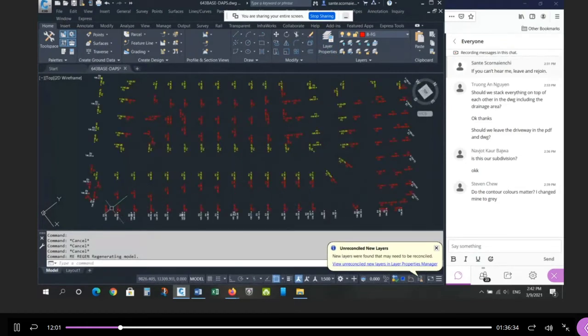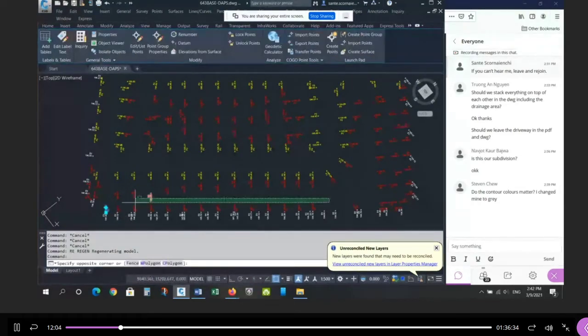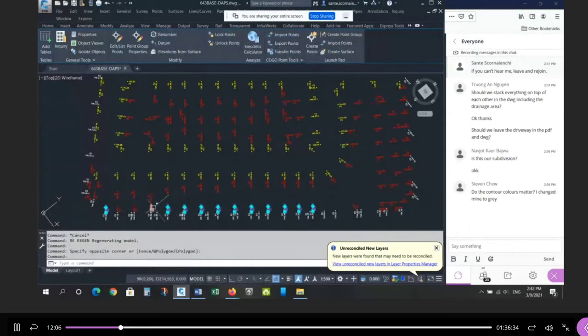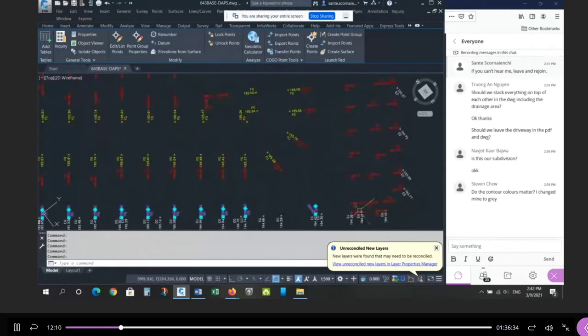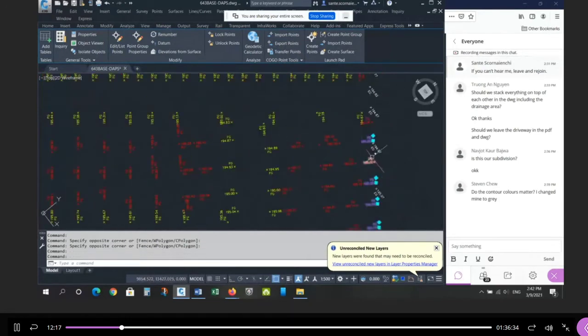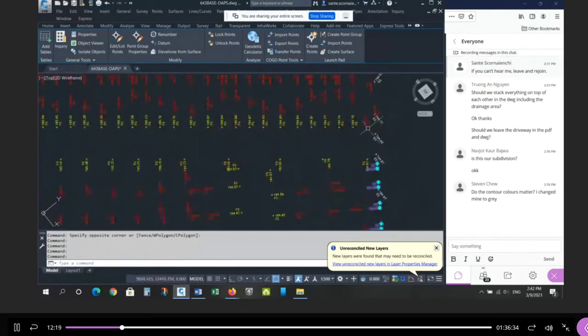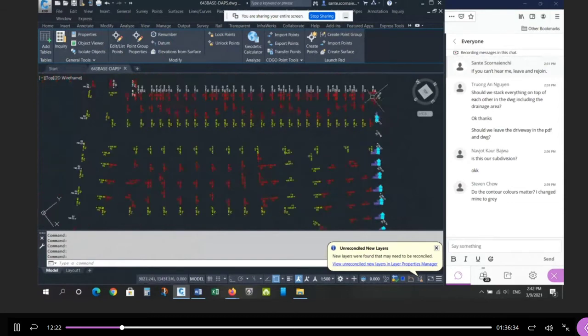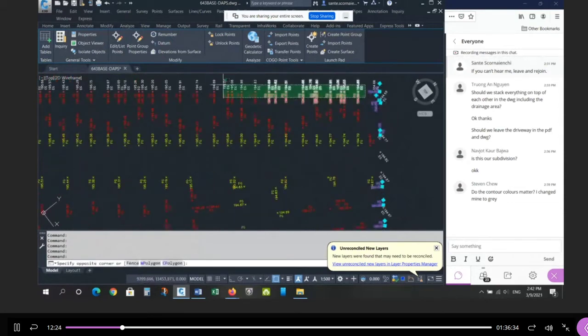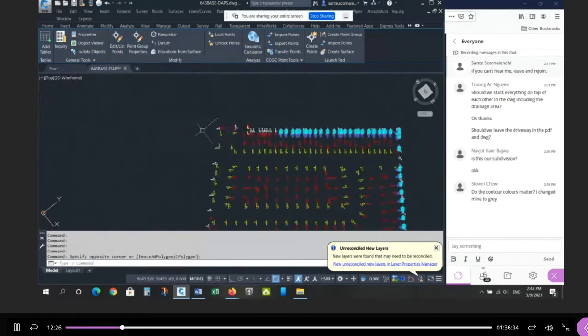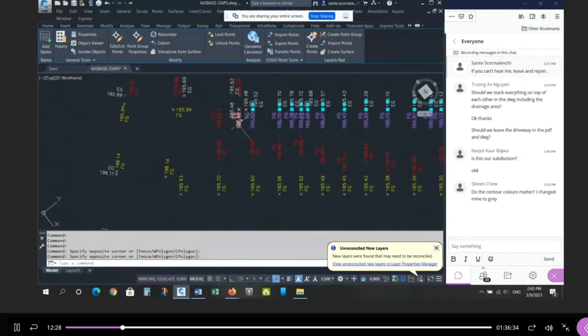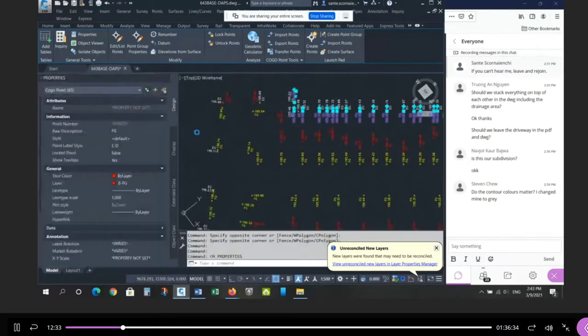Okay, then the actual interpolated elevations at the back, these design elevations interpolated from the back, they would be on a separate layer, right? So these rear lot ones that come from the perimeter, those are on a separate layer. And again, I'm just giving you a general idea, right? Everything we designed back here along the original perimeter. So all of these back here are interpolated. Okay, those would go on a separate layer as well.